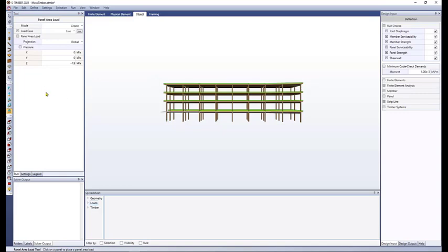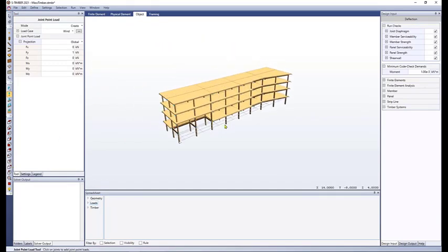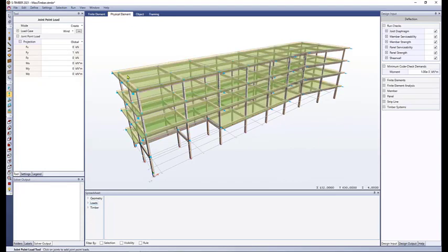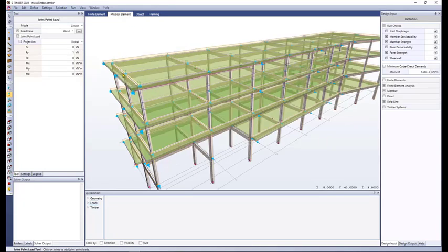And the last load case I'm going to define is the wind load. So I select my wind load, make sure I specify my joint load. I'm going to apply some joint loads, not in the negative Z direction, but in the Fy, about 1 kilonewton. And this will be assigned to every node except for the supports in my model. And you can see here, you can use the physical element view to see every node which has this load assigned.